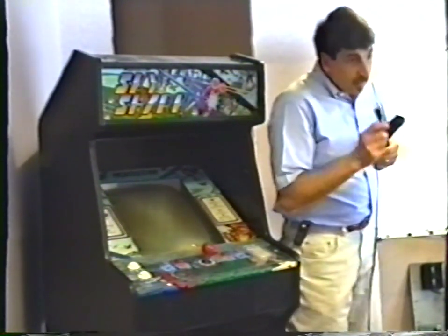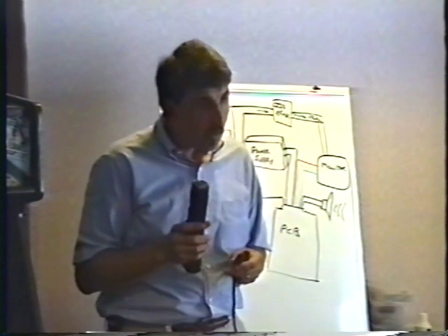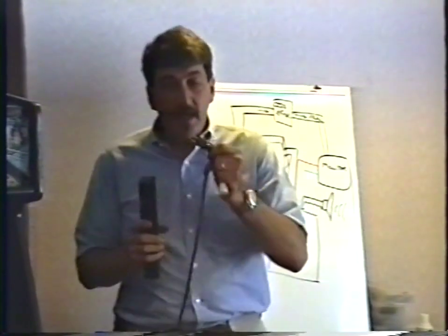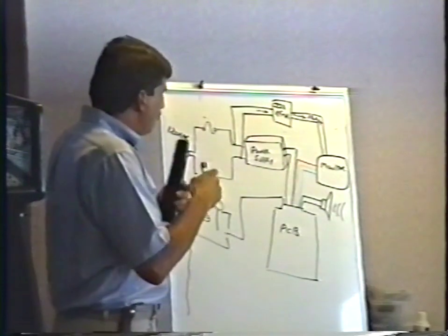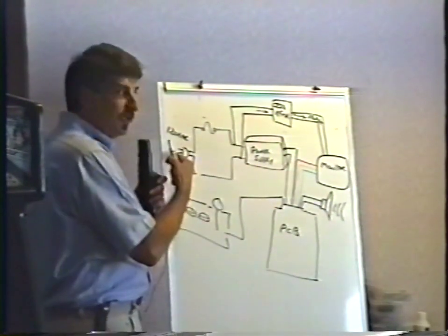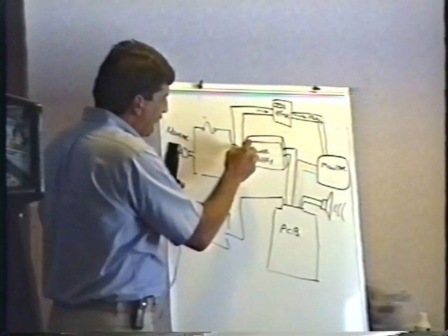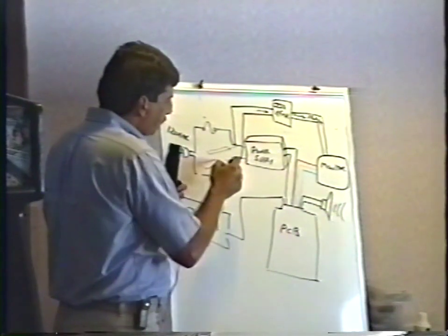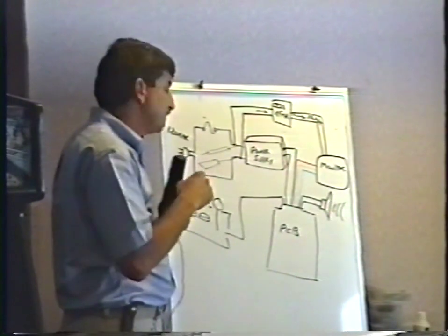Now, here's what I do to troubleshoot it. If I have a choice of two different ways to troubleshoot something, with the power on or power off, I always do it with the power off. Here's what most people do to check this out. Most people will plug this into the wall, and with the meter set on 120 volts AC, they'll put their meter probes here and here and measure the voltage there. I mean, that's what most people do. You go, oh, well, there's no voltage there.